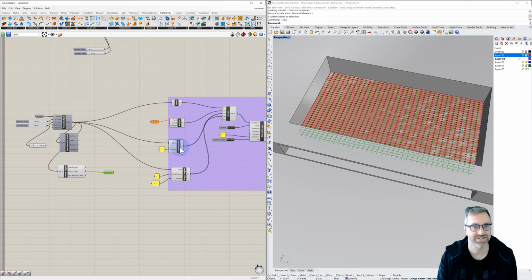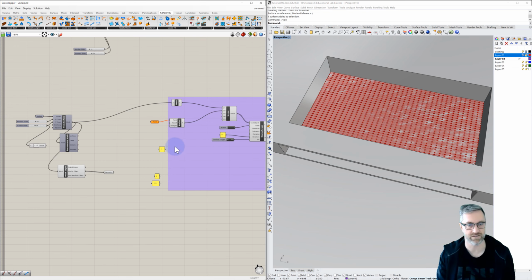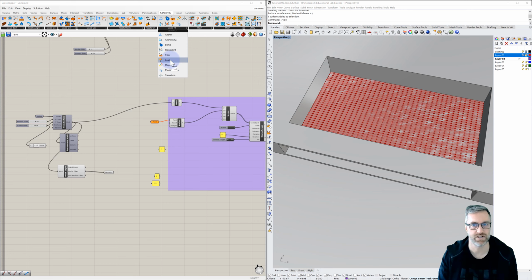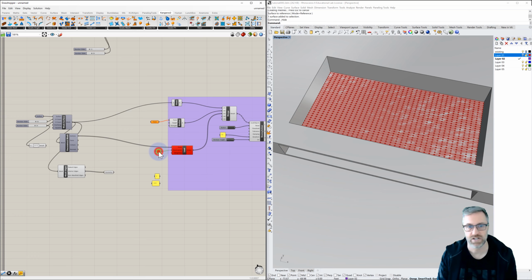So let's do a couple of things. Let's swap out our loads and our edge lengths. We started with one way with our catenary model, and we'll kind of revert to that this time around. So for our goals, let's grab the load. And this time around, with the way that we load these, let's grab all of the vertices from the deconstructed mesh. We can load this into our merge, and rather than it being a negative number this time, we're going to use a positive number. So our force vector, which that's not liking so far, let's set this to be 0.5, so it's positive.